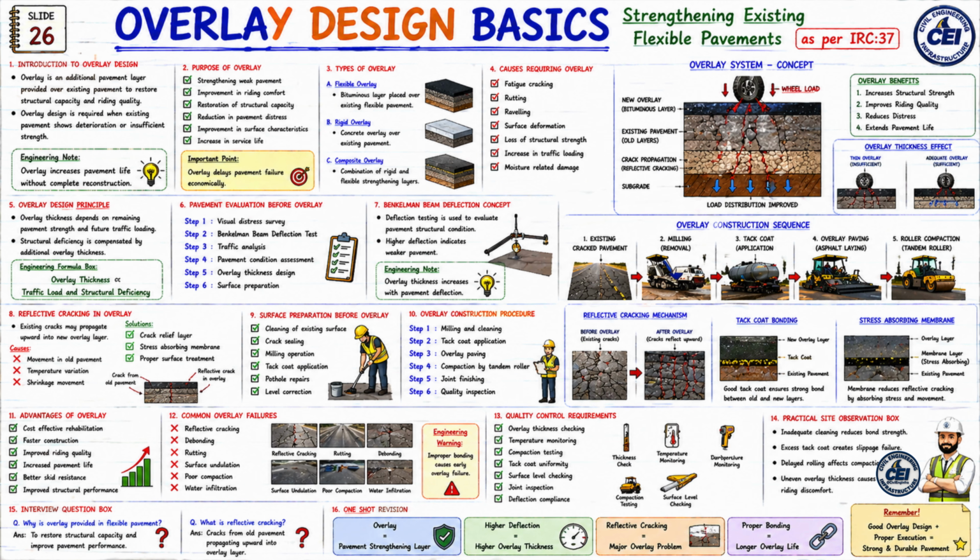Now let us look at the ninth topic. Surface preparation before overlay. What is done in surface preparation before overlay? Cleaning of existing surface, crack sealing, milling operation, tack coat application, pothole repairs, level correction. And surface preparation is very critical for proper bonding.